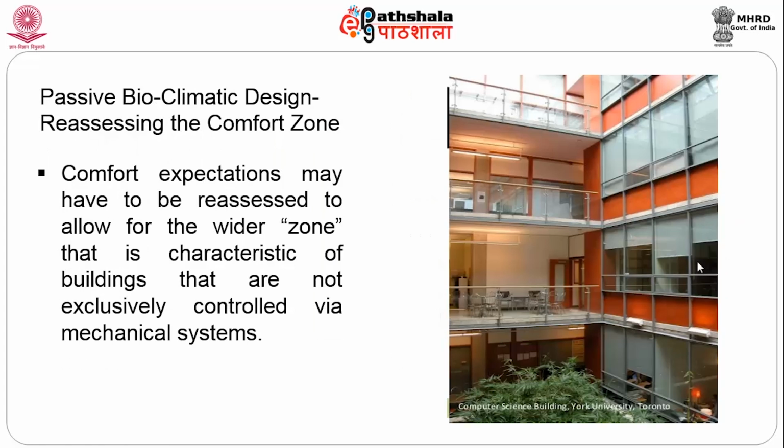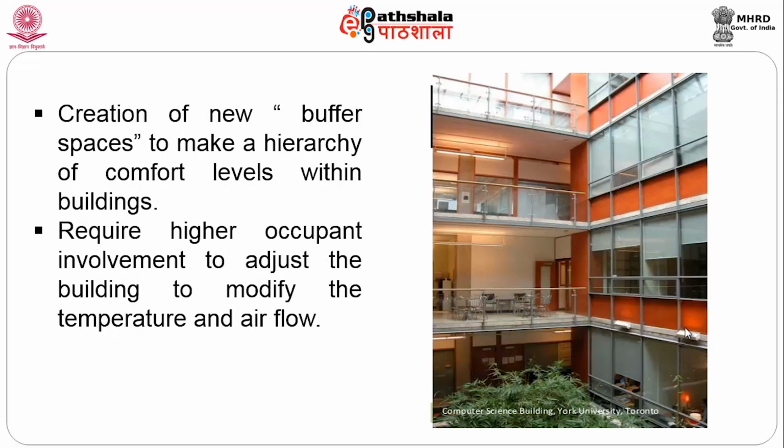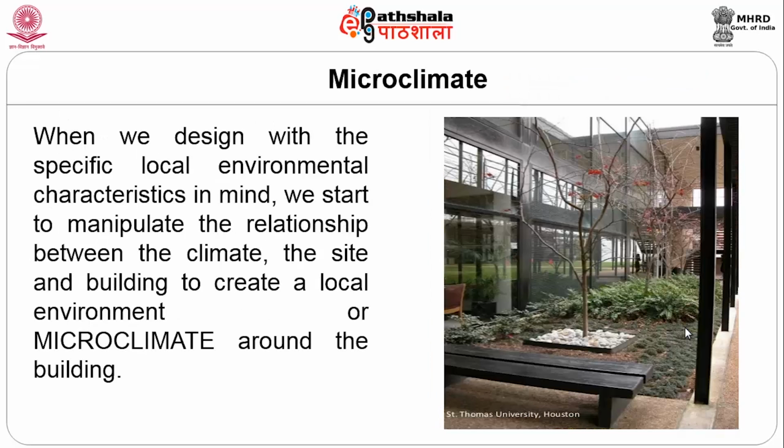Here we have an example of passive bioclimatic design, and how we reassess the comfort zone. This again is the computer science building in York University in Toronto. Comfort expectations may have to be reassessed to allow for a wider zone, which is characteristic of buildings that are not exclusively controlled via mechanical systems. It involves the creation of new buffer spaces to make a hierarchy of comfort levels within the buildings. It requires higher occupant involvement to adjust the building to modify the temperature as well as airflow.